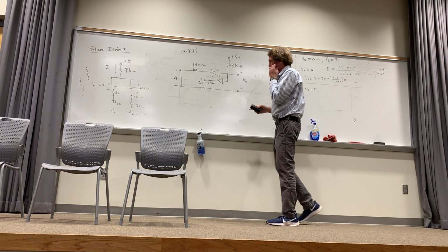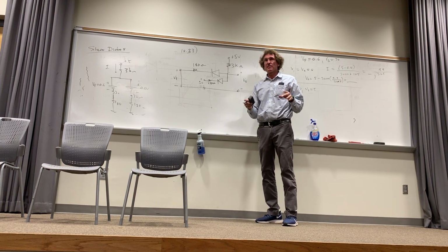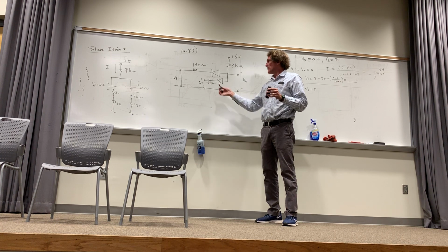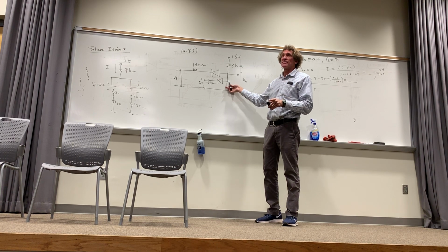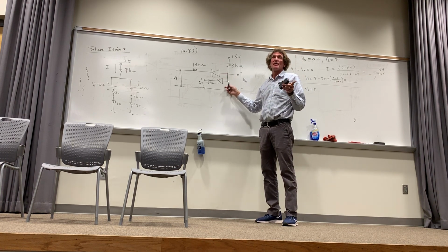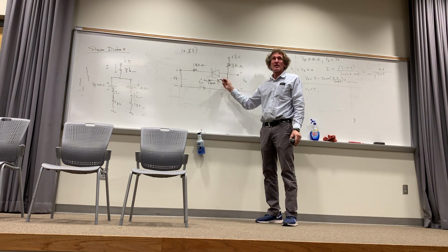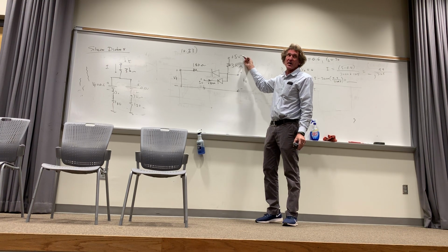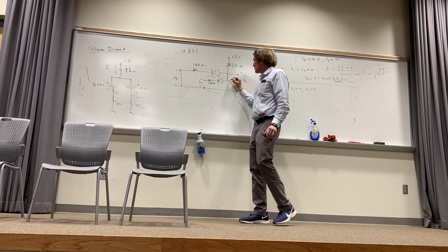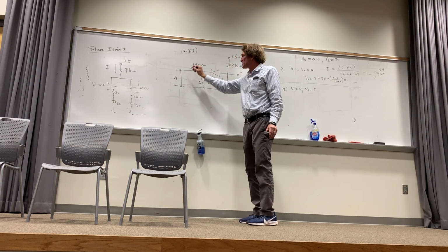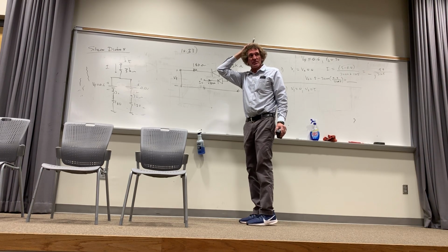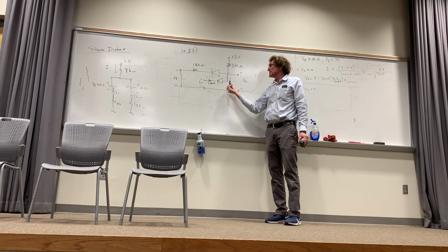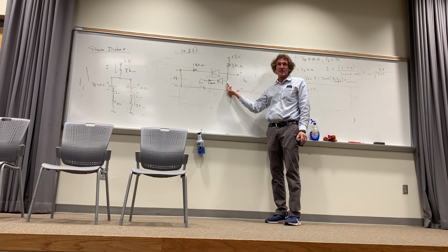You're going to get the hang of this in a hurry. Now, this is what it looks like. Are you with me? That's still grounded. Now, hear me. If this is 5 volts, right? The voltage on this side has to be greater than 5 for current to flow in that direction. Actually, it has to be greater by what? 5 plus 0.6, correct, class? Is it ever going to get there? No, the most voltage we've got to work with is 5. Do you all see that? So that means no current flows that way, and all the current flows this way. Does that make sense? Give me a show of hands if you see this. Y'all with me on this one? It can't flow this way because you need at least 5.6 volts there for anything to flow in that direction.